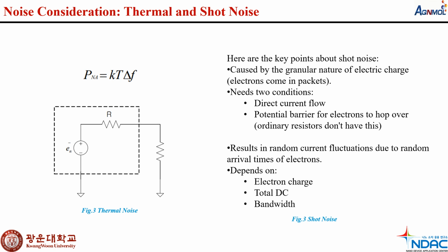This noise power is independent of frequency, making it appear white across the spectrum. The term available noise power refers to the maximum transferable noise power to a load. A noisy resistor can be modeled as a voltage generator in series with the actual resistor.